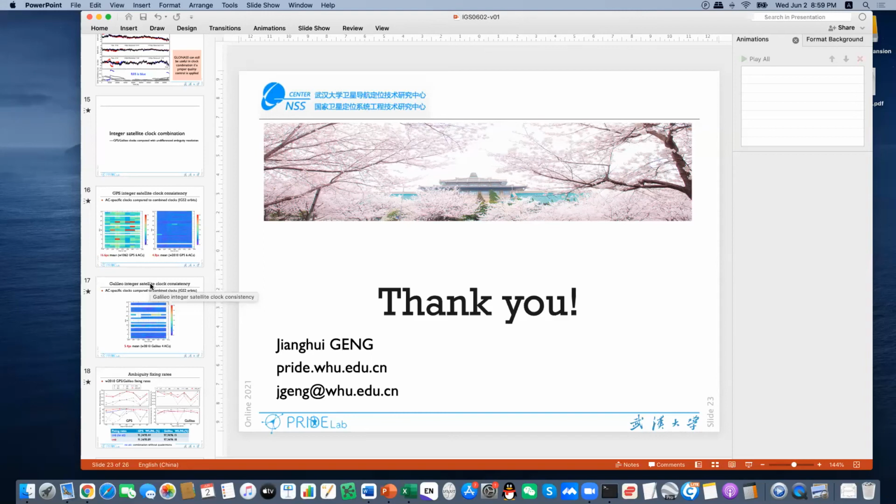In the case of multi-frequency solution, we can also use the multi-frequency observations to improve the convergence efficiency. But the multi-frequency solutions cannot perform as well as the atmosphere augmented PPP solutions, because we have the wide lane and extra wide lane ambiguity resolutions, and the noise of the two combinations is quite large and cannot effectively constrain the narrow lane ambiguity resolution. But anyway, if we can combine both strategies, then we can have the best performance to speed up the convergence of precise point positioning.